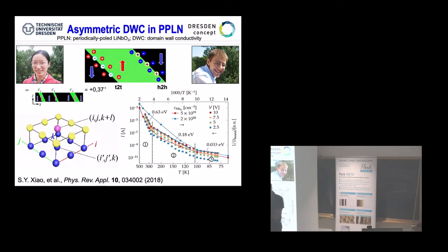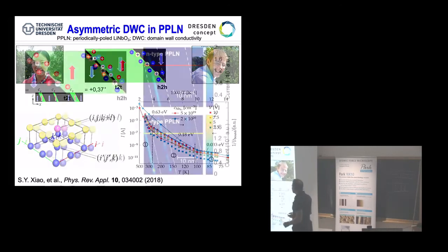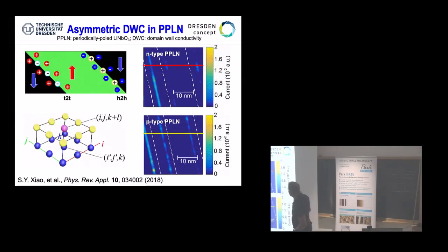So we take this value, put this into the modeling of the hopping mechanism, and what comes out is exactly this one here, that we find there can be really right-handed, or the right domain wall really enhanced currents in the model. This is a model only. And hence these are really the electrons, hence it must be an n-type conductor. We can also do the modeling for the holes, and hence actually oppositely to that one, you see nicely, it's the left side. So if you go for hole transport, we see that the model is really good, tunable.